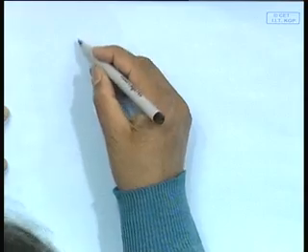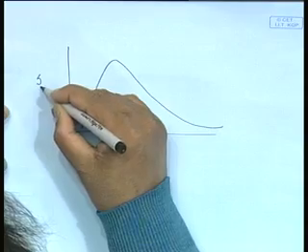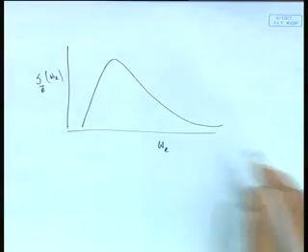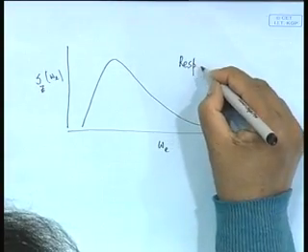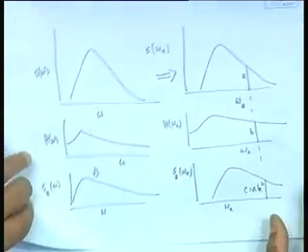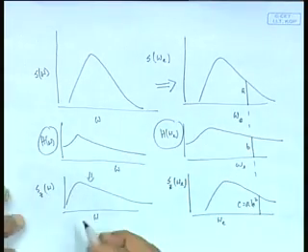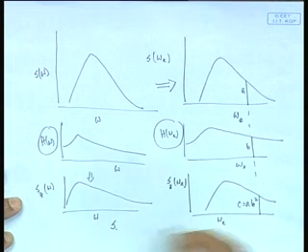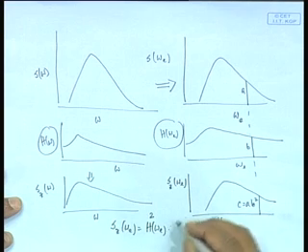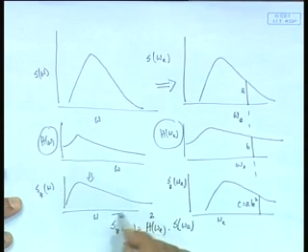So, let us look back at the response spectrum. Again I am calling it heave, but it can be any response, which we will come to in a minute. Let us take this forward speed case only. So, this is my response spectrum. But before that, let me tell one small thing that I keep missing. I call this h omega, right? And what did I say? I say that S z omega e equals h omega e square into S omega e. This is what we have been saying, right?